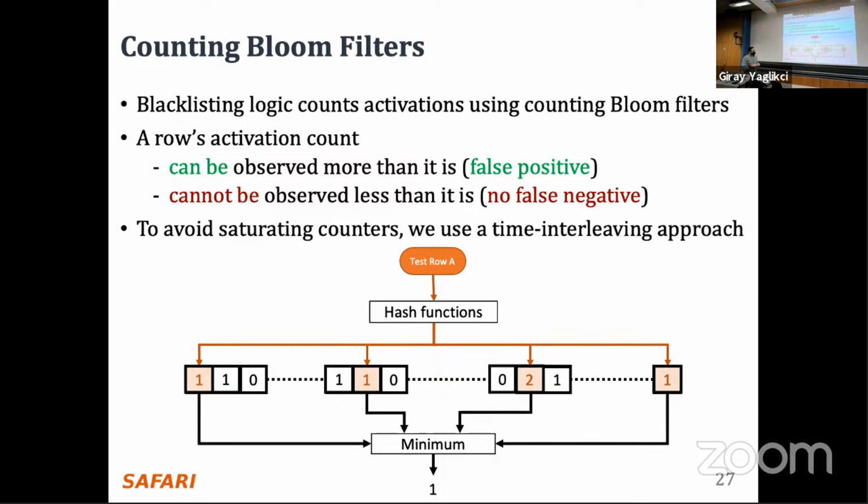But since we do not decrement them, now we have another challenge. These counters can saturate because they are not infinitely large. We use a time-interleaving approach, and we employ two counting Bloom filters to periodically reset them without losing information. I will explain that next.